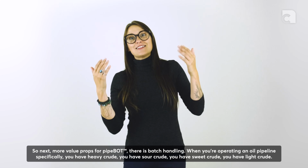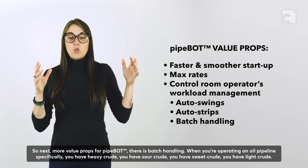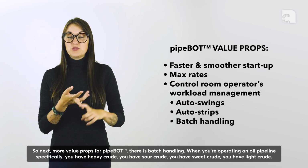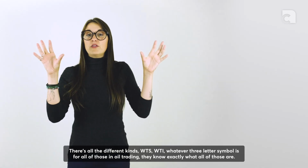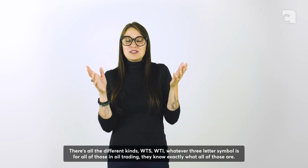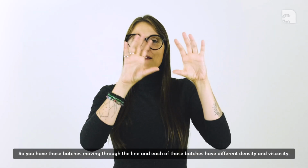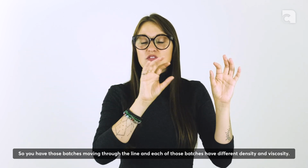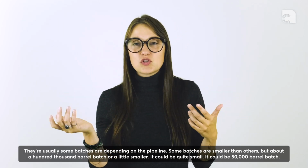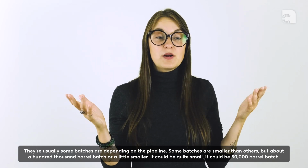Okay, so next, more value props for pipeBOT. There is batch handling. So when you're operating an oil pipeline specifically, you have heavy crude, sour crude, sweet crude, light crude, all the different kinds, WTS, WTI, whatever the three-letter symbol is for all of those in oil trading, they know exactly what all of those are. So you have those batches moving through the line, and each of those batches have different density and viscosity. Depending on the pipeline, some batches are smaller than others, but about a 100,000 barrel batch or a little smaller, right? Could be quite small, it could be a 50,000 barrel batch.